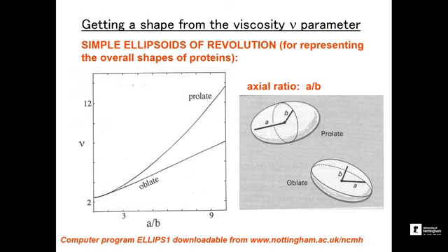That was at 20 degrees centigrade. Then we put the heaters on full blast and follow the change in the relative viscosity. You've got to correct for the change in the solvent, the water, but there are tables to help you do that.